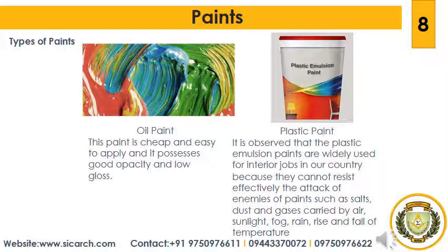It should be remembered that the oil paint should not be applied during humid and damp weather. The presence of dampness on wall surface also considerably affects the life of oil paint coating. It is advisable to redecorate surfaces finished with oil paint with a coat of fresh paint only. So the layer of old oil paint serves as a foundation for the fresh paint.